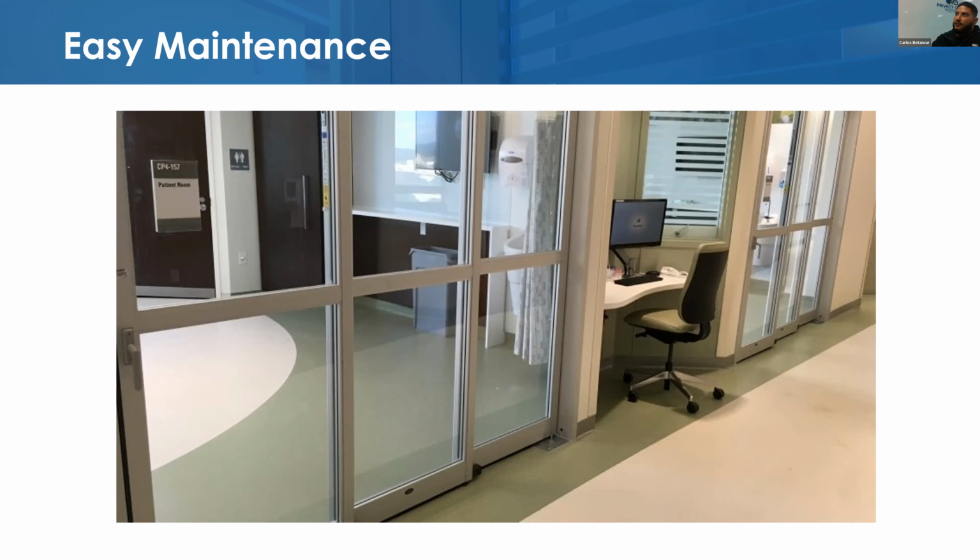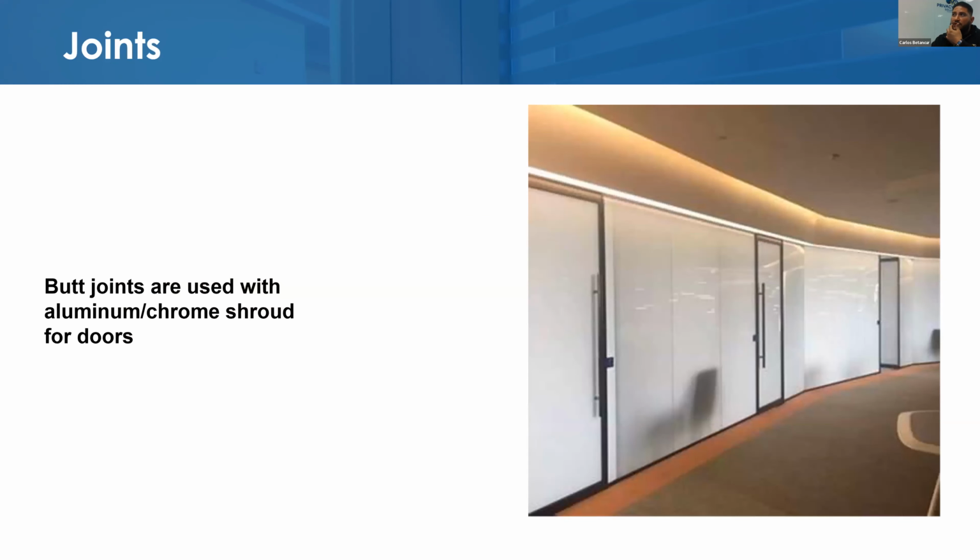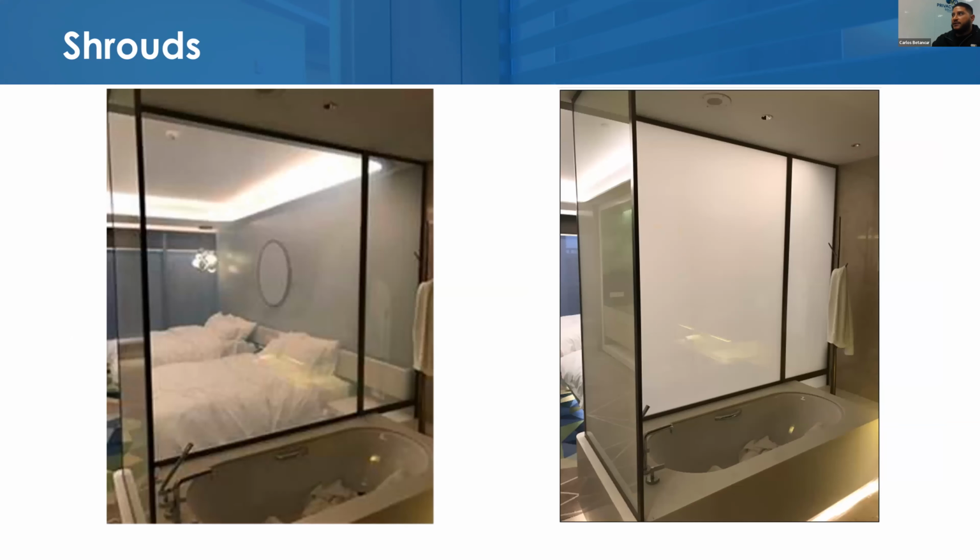Okay, awesome. So besides instant control of privacy and single or double glazed panels, switchable glass is easy to maintain, comes in flexible production sizes with fire rated or lead glass or low iron glass, and it can be ordered with various shapes for unique design applications. So you also have different examples of installations here. So here you have some butt glazing where you have this as an office partition. You also have examples of where it's installed in an environment with condensation, moisture, humidity. Basically, what this is pointing out is that all four sides do need to be protected in such an environment.